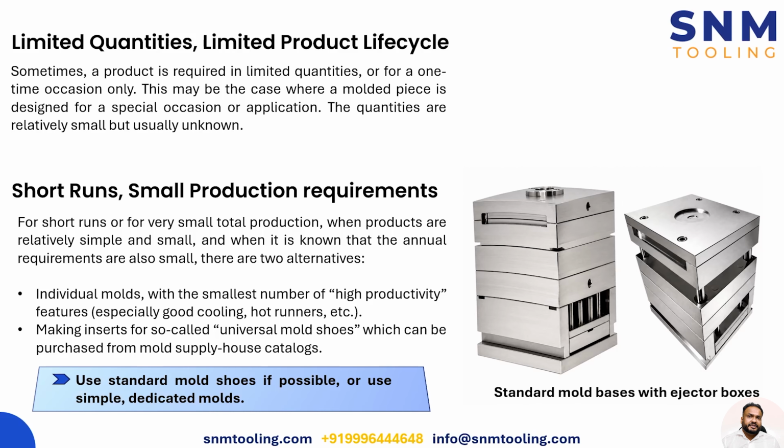So standard mold bases are readily available, and we also have this special mention to use standard mold bases because, as a matter of fact, mold base and mold shoes are one and the same thing. The reason for mentioning standard mold shoes or bases is because those are accepted globally for different inserts, right? And that would certainly help the molder save cost on buying different mold shoes or mold bases for different products because each product is simple, doesn't have many undercuts or any undercut for that matter.